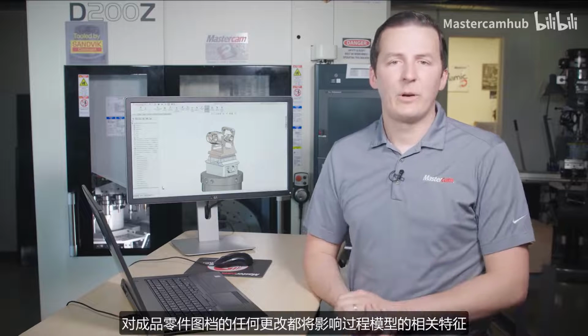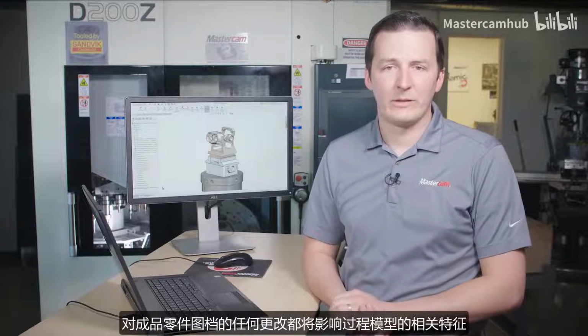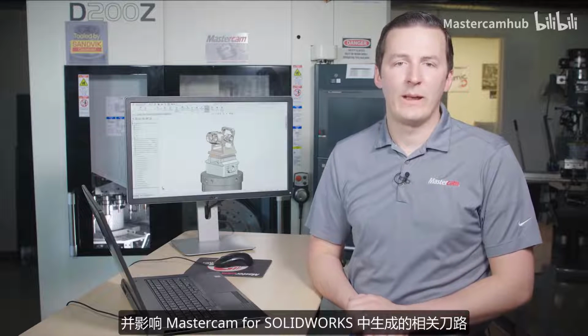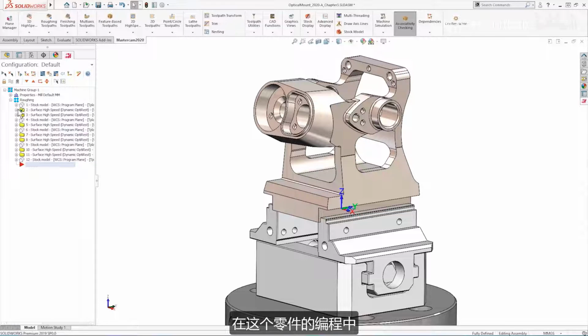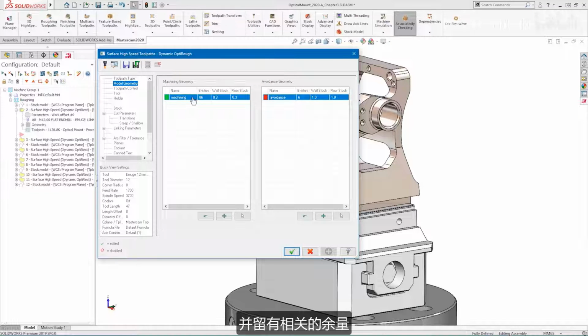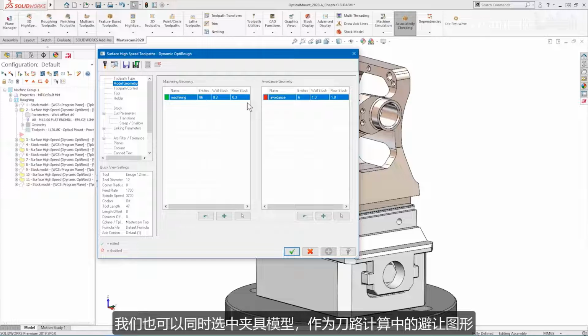Any changes to the finished part file would prompt changes to the in-process models, which would then prompt changes to the corresponding Mastercam for SolidWorks toolpaths. The OptiRough toolpaths in this process reference these SolidWorks assembly components as machining geometry with a certain amount of stock to leave behind. We can also select the fixture setup to be used as an object to avoid altogether.